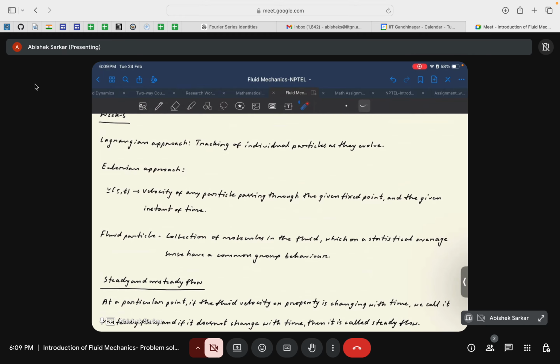And from this you understand that as we track the particles as they evolve, the velocity field and the acceleration field in this case for Lagrangian approach is only a function of time. The velocity field may be decomposed into x, y and z components, but each of the velocity components, that is u, v and w, would be a function of time only. So we will track the evolution of the velocity field with respect to time and see how each and every component of the velocity field varies with respect to time. Basically, so I will just write it for your reference.